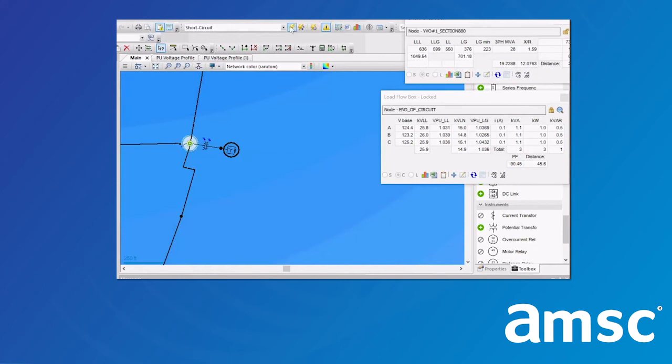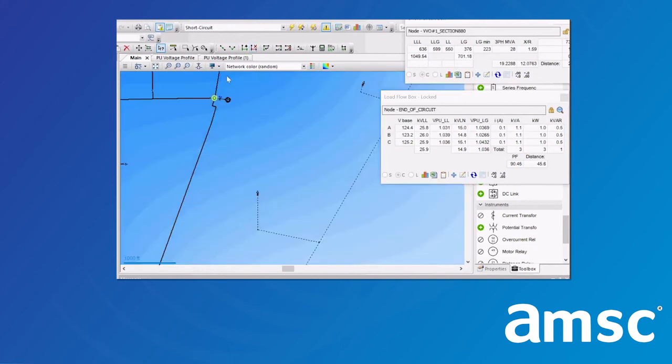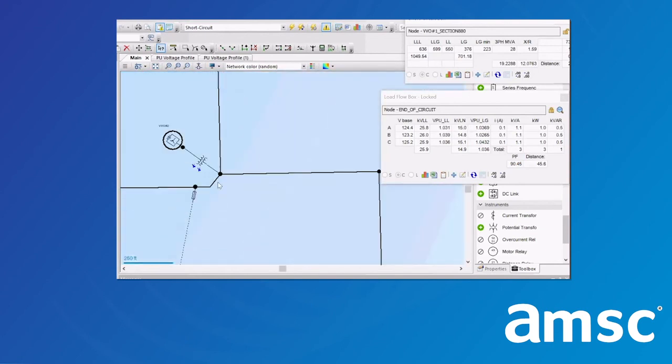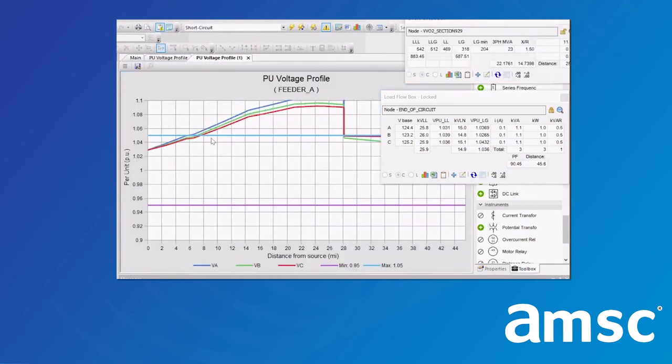In this case, the fault power is around 28 MVA, XR of 1.6 at the first VVO location, and 23 MVA, XR of 1.5 at the second. So I would approximate that each VVO will provide about 3% boost or buck at their respective locations. And when we look at the magnitude of overvoltage here, we're using two VVOs because the overvoltage is in excess of 3%.